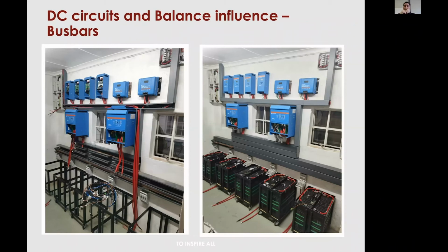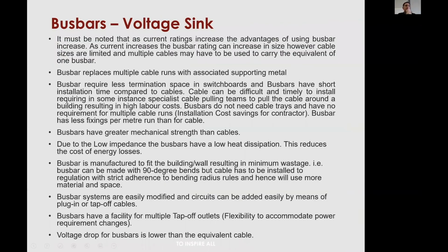So as long as those BMSs are turned on, there will be a current bringing voltage and energy across the bus bar from battery to battery. And in that manner, each of these batteries, without even trying, synchronize up to the same voltage. And that's one of the virtues of this idea of a bus bar.